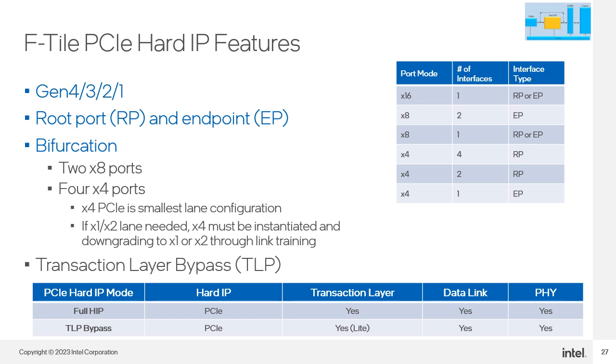Bifurcation, if supported by the system, allows a single physical PCIe port to be split and recognized by the system as multiple smaller individual ports. So each of the 4 controllers would be recognized by the system as a separate port connection, though they are actually using different lanes of the same physical connection.